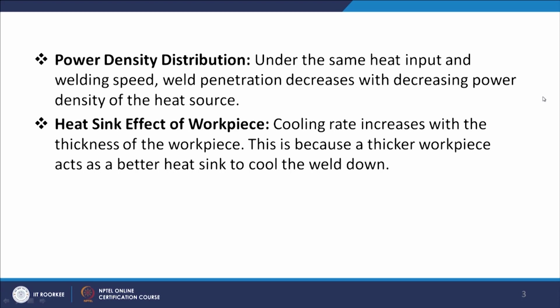Now, the next parameter which we are going to discuss is the heat sink effect of the workpiece, and in that the cooling rate will increase. Cooling rate increases with the thickness of the workpiece, because a thicker workpiece acts as a better heat sink to cool the weld down.